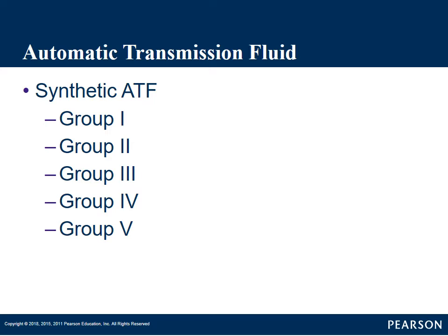They are more expensive, but the idea is they're supposed to last longer, and they're supposed to give you better properties when it comes to viscosity and temperature. But definitely, if your transmission calls for it, you would want to put synthetic fluid in it.